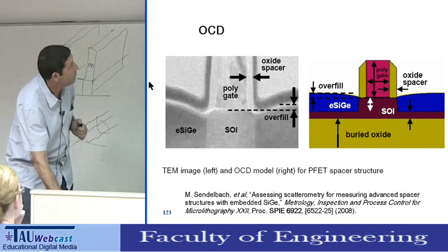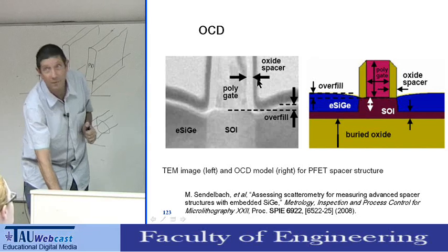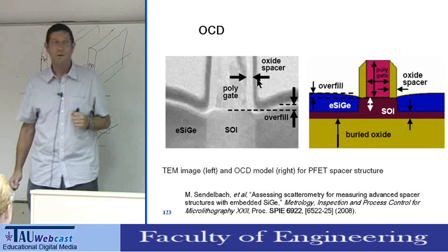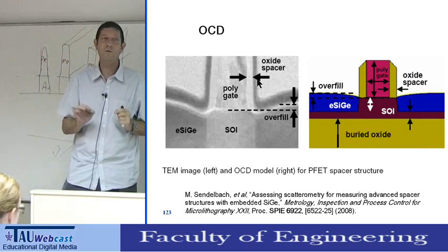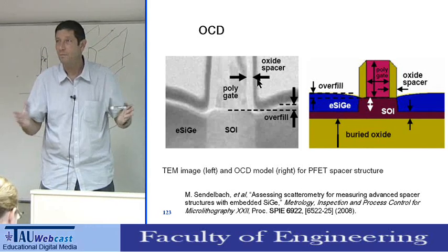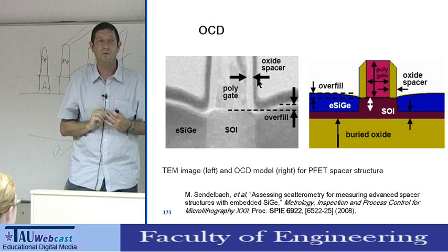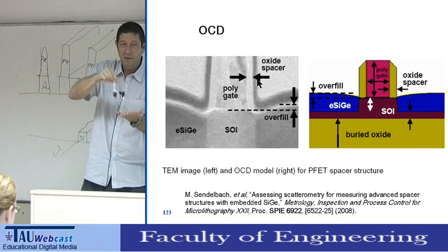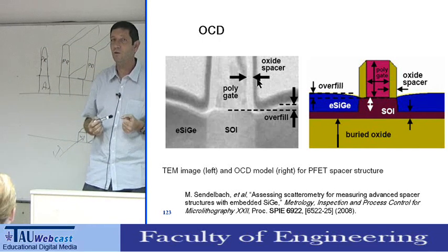And I would like to measure the width of the poly after the lithography. This is the real critical dimension measurement. So one option is to use SEM, to use the beam of the SEM to scatter it. The e-beam scatters, I measure the secondary electrons and I get a very nice image.